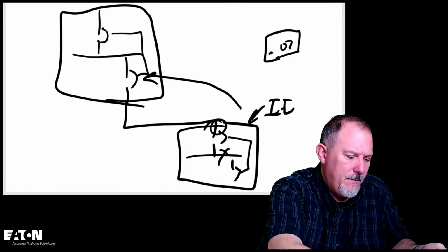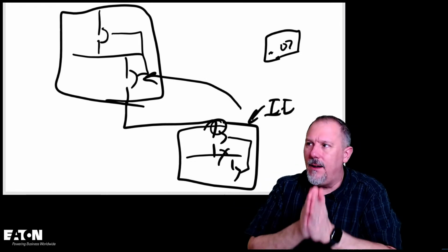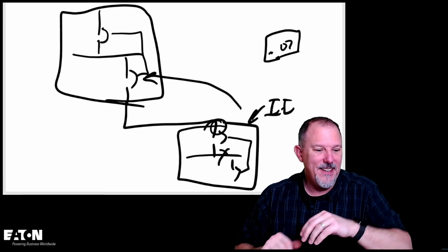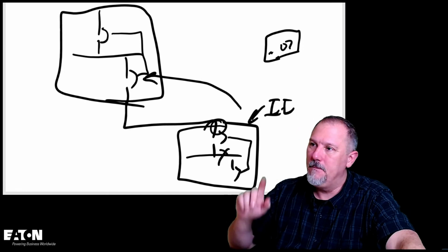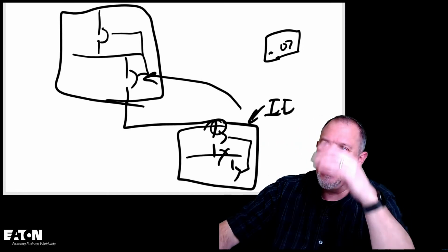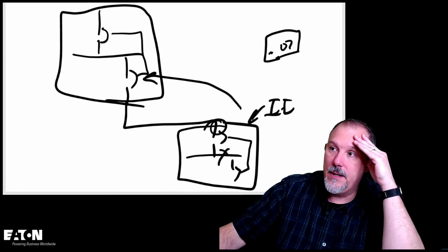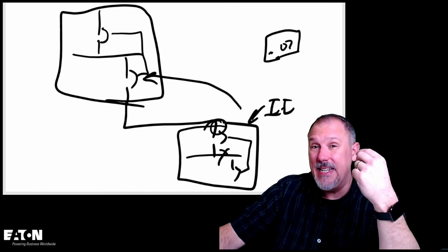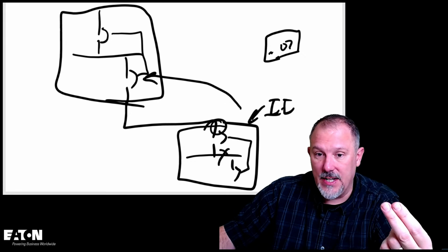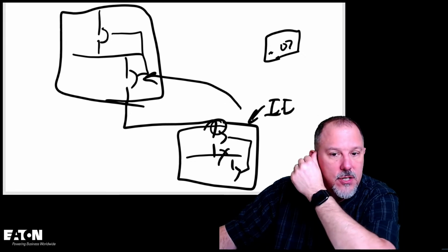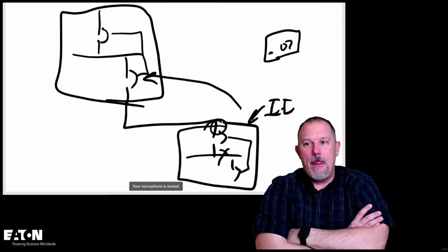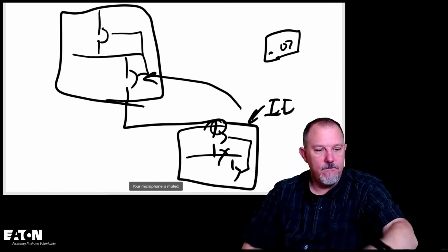All right, so we talked today a lot about this diagram, right? We picked our overcurrent devices. We talked about the ampacity. We did a conduit sizing. Do you think ZSI should be a permitted solution for 240.87? Well, okay, Ryan, I have an opinion.